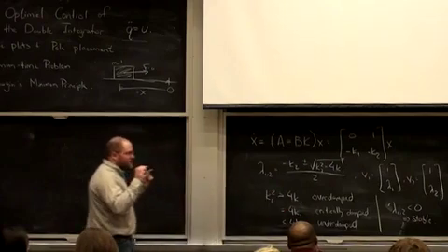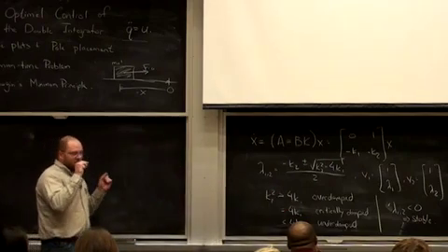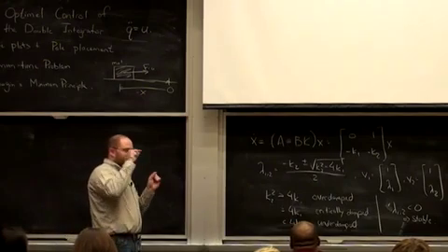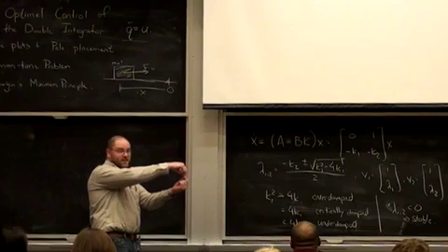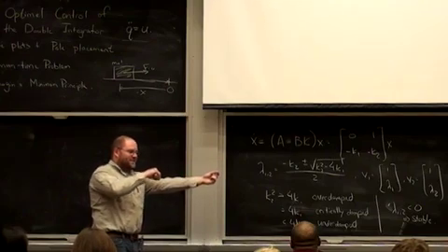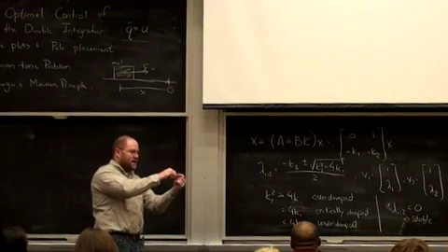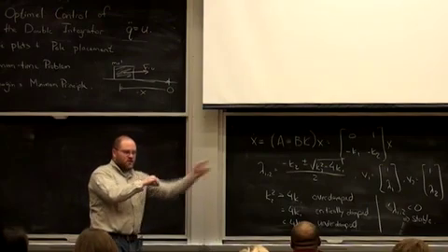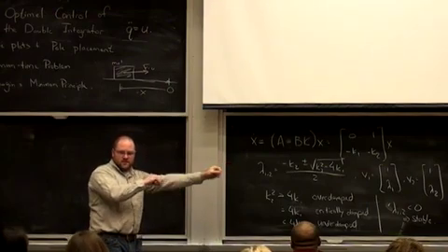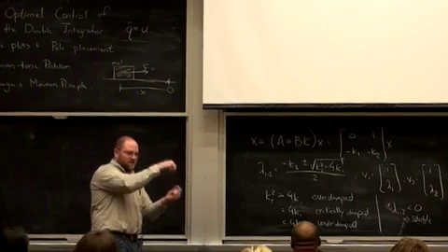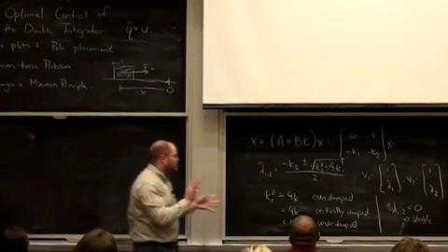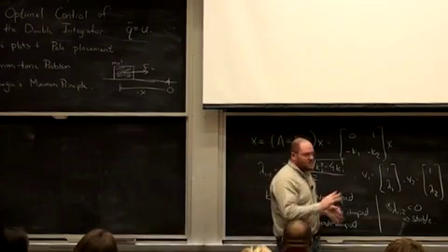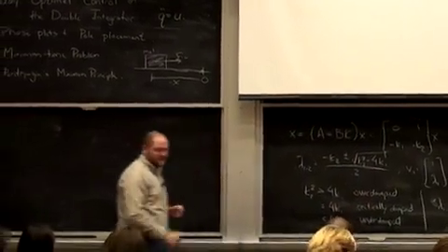So what you get is, for very small feedback gains, you get oscillations. As you crank it up, the poles connect in the left half plane, and then they separate, right? And as I keep turning up my gains, one of them creeps towards the origin, the other one goes off really far to infinity. Right? So for those of you who think about poles and zeros, this is exactly the same way to say that. I didn't do a root locus because I was changing two parameters, but it all connects, okay?